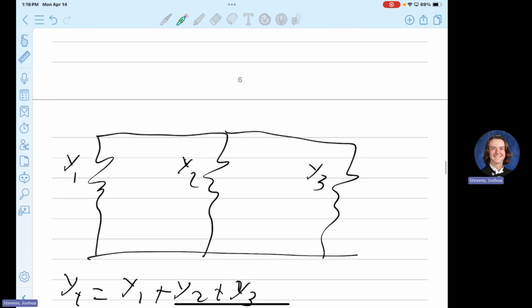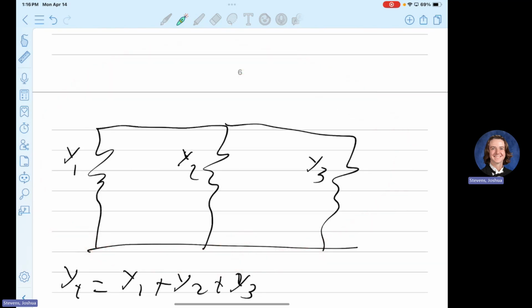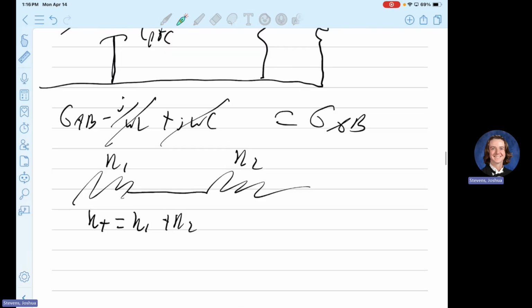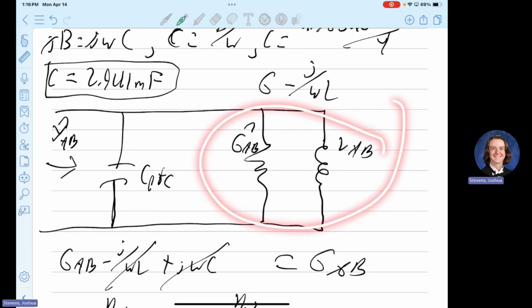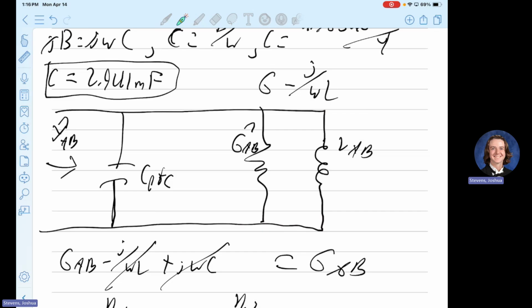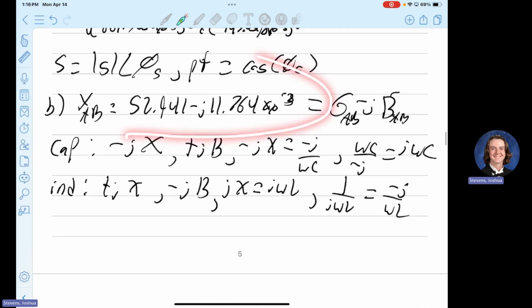Because we denoted the whole thing, right? You add two admittances like they're in series for impedances. So these would basically add together just like simple addition because they're in parallel and they have to add together to get this value. That makes sense?